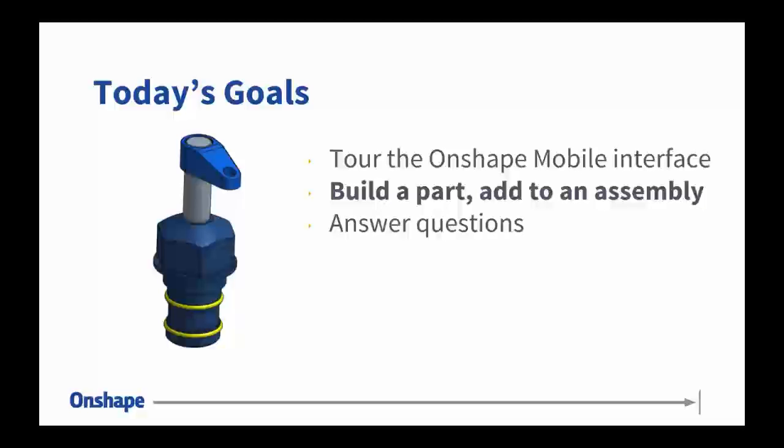Quick question. Can I take apart an Onshape and open it in SolidWorks later? Yes, you can export Onshape parts, for instance, as SolidWorks parts, SLDPRT files. They will not carry over the sketches and features, and that's an important thing to point out, but you can export a native SLDPRT file from Onshape.